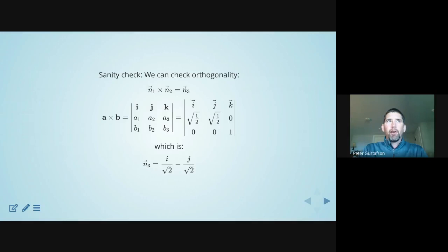But you could, if you wanted to sanity check your principal stress values, now that you know the unit vectors, you've gotten to the end, you could go through and use the Cauchy stress formula. You could dot the stress tensor with the unit vector. You'd get a traction vector. You could dot that traction vector again with the unit vector. So you're going down 2 ranks by doing 2 dot products and get to the principal stress value. That would be a way to sanity check that answer as well. I don't demonstrate that here in the lecture notes, but it's fairly straightforward.